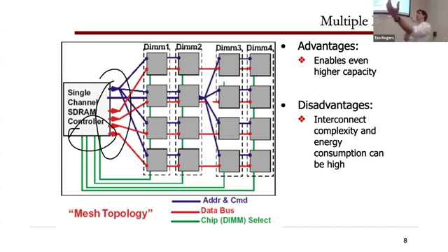If you buy a 1 terabyte DIMM, if that's even available, it's probably available today. It's way more expensive than buying 2 512 meg. No, I don't think they're that big. What's the biggest DIMMs? Last time I bought them, I think it was like 128 or 256. 64? 64 are the fastest ones, 128 are the slowest ones. Yeah. So these CPUs that have terabytes worth of storage, there's a whole bunch of DIMMs in there, right, to provide that capacity.